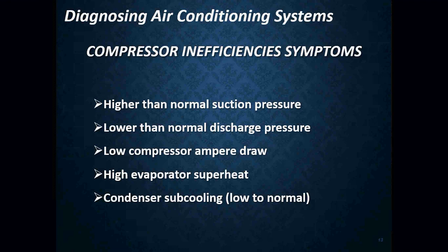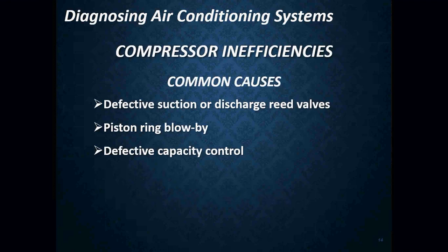So our refrigerant undercharge, our refrigerant overcharge can also cause our compressors to be inefficient. And when that happens, you're running at a much higher amperage. You're making that unit run harder than it absolutely needs to.